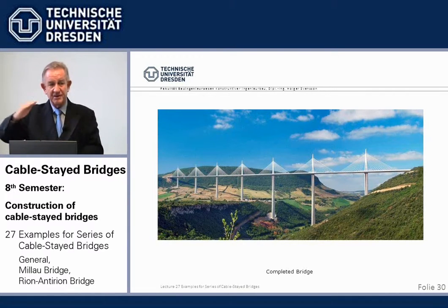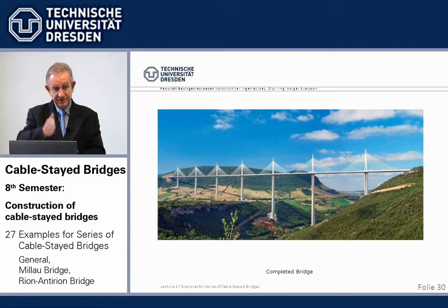On the other hand, by cutting a slot into the piers, roughly we have 1/8 of the horizontal resistance. So we have very flexible piers so that they can move with the beam in temperature.